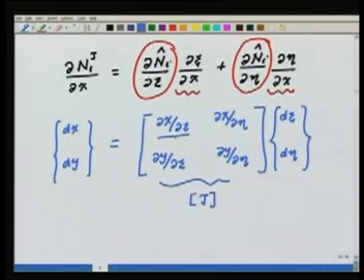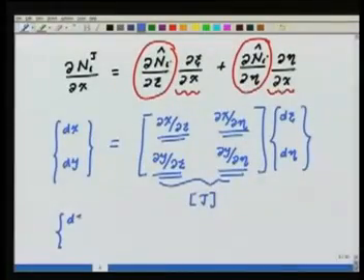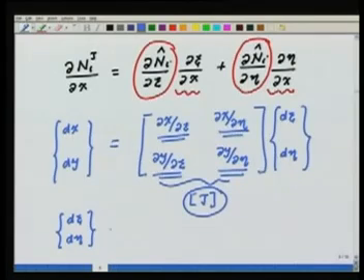These quantities we can compute by using our bilinear mapping, that is x in terms of x1, x2, x3, x4 and the shape functions of psi eta. Similarly, y in terms of y1, y2, y3, y4 and functions of psi and eta. So then simply we can write d psi d eta, and look, this Jacobian is now going to be a function of psi eta. So then this will be equal to Jacobian inverse into dx dy.